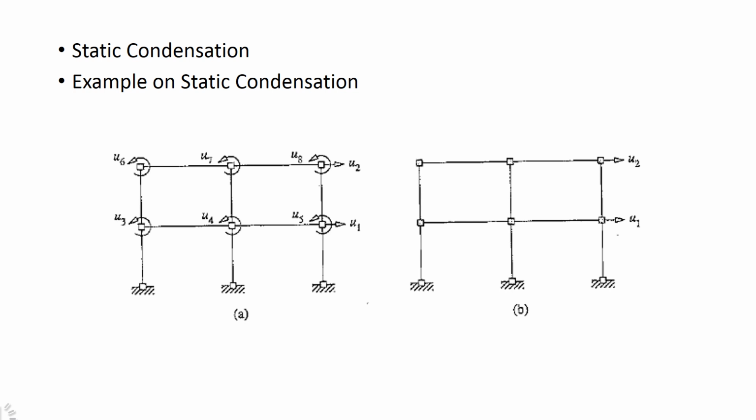For example, one of the assumptions was that the axial deformations of the columns are negligible and the beams are strictly rigid. Thereby, we could eliminate many degrees of freedom, both vertical translational as well as horizontal translations, which were to be concentrated at certain particular places.